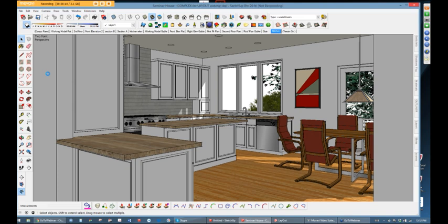And you might also notice here in this drawing that this is set in 2-point perspective. You can see it up here in the top left corner. What that does is it makes all the vertical lines in the drawing vertical instead of kind of canted off in any direction. The reason for that is clients typically, and even I, in terms of exhibiting this kind of drawing, don't really like vertical lines to be canted. So that 2-point perspective will maintain those lines vertical. It's probably not totally realistic, but it's easier to look at.